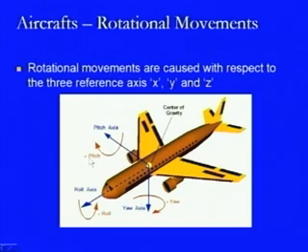The third axis, which is the z axis, which is perpendicular to both of these axes, that is the roll axis and the pitch axis, is working like this. Now, when we talk about this axis, the motion which can be there with respect to this aircraft is taking a turn either in this direction or in this direction. So, with respect to a vertical axis like this, it can move in this way or in this way. So, this is the axis about which the aircraft takes a turn, maybe in the right hand direction or maybe in the left hand direction.